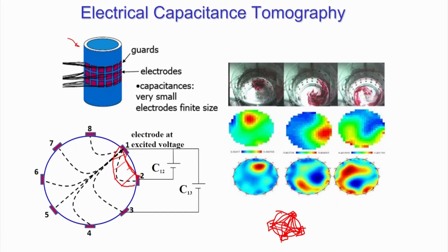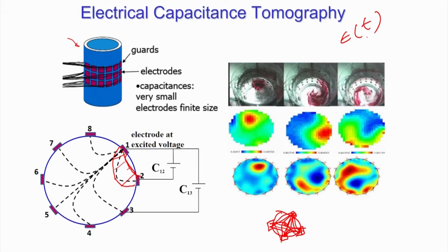But because its temporal resolution is very high, you can see how the mixing between the two phases is taking place, how the volume fraction is changing with the time. That can be measured with a very high accuracy. Ideally, it can measure the epsilon with x and t in one go, because you are covering the whole volume or kind of a zone of interest. Within that zone of interest, it can give this information because you are covering the entire cross section, not like an intrusive technique where you are putting the probe inside, and that is why it will just be able to get the information at that location. So, that is not true here.